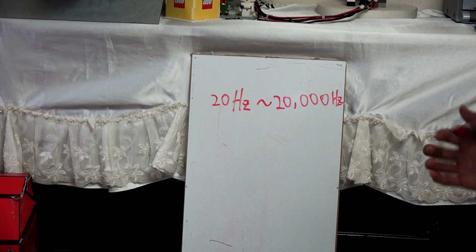But before we do, pulseIn returns the time in microseconds, so we have to change this microsecond to a second, and we have to change this meter to centimeter to make it a smaller unit.